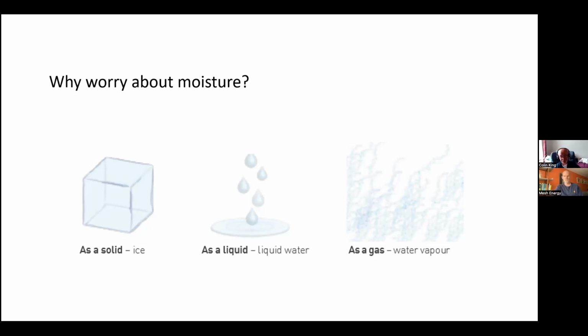And then we have liquid water, which is really, when you're looking at liquid water, we're looking at things like falling damp, timely maintenance, actually maintaining the properties, cleaning the gutters, making sure all the seals around the windows and all the penetrations from services don't allow water to actually get into the building. And then we deal with the moisture as a gas, water vapor, because that's where we get that internal relative humidity right to put this building into that moisture balance.